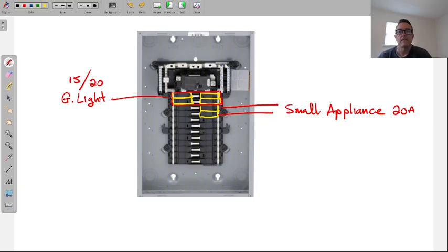And then knowing how to move those breakers around using those tandem breakers, the ones that you can stack 2 circuits on one breaker. They come with 2 little handles on one small breaker. I had to add a bunch of those. But the point to that is also that when these things are calculated, all of these minimums that we're giving, this is why it's a good idea to also go a little bit above the minimums too. Add an extra general lighting, add a couple things, just so that your main breaker could be large enough to handle future things.